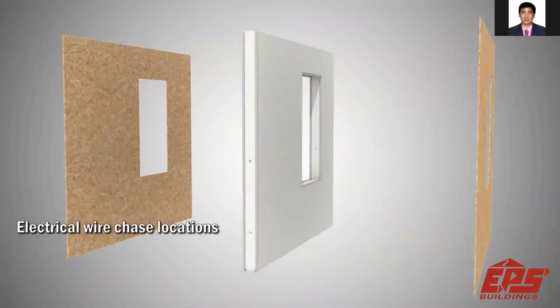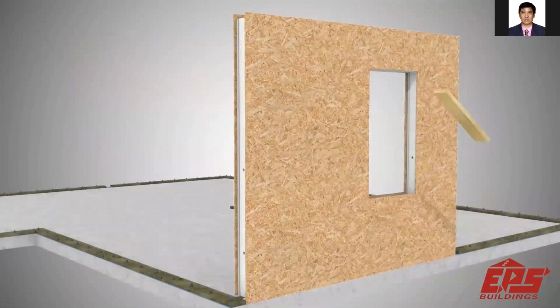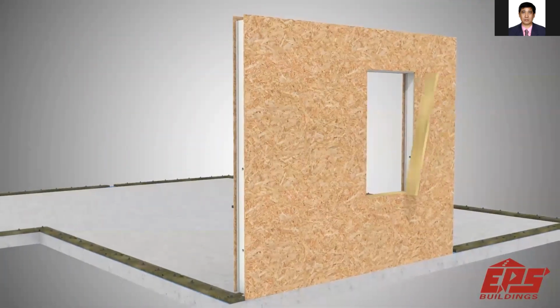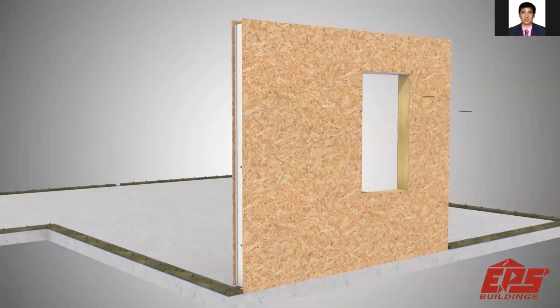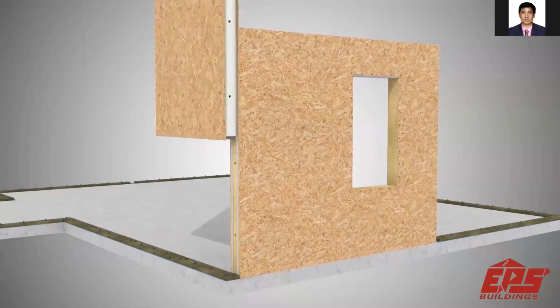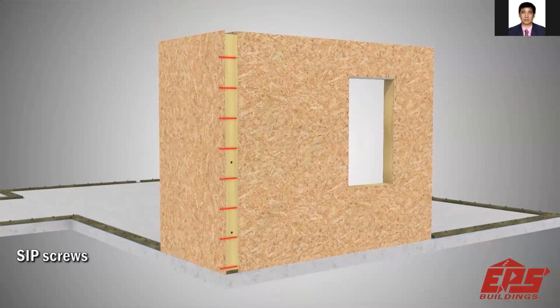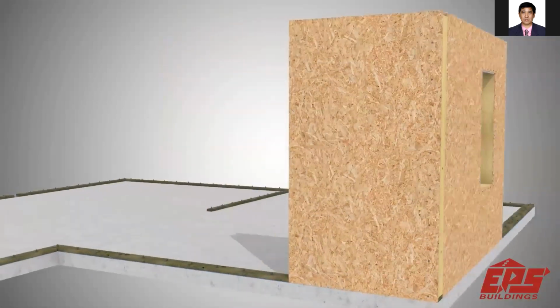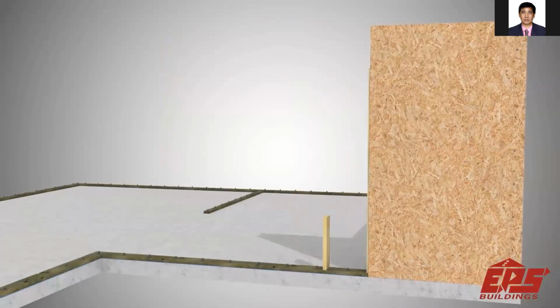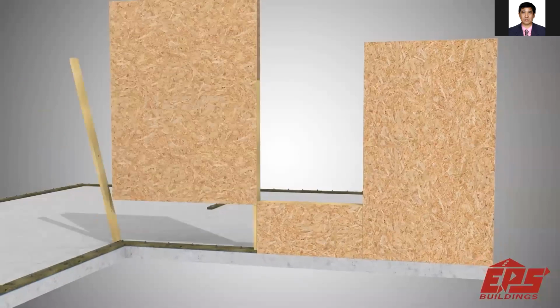Optional electrical wire chases can be placed horizontally or vertically in the panel. Wall panels are installed over and fastened to a base plate. Assembly starts by fastening corner panels together using both interior and exterior surface studs and SIP screws. Sealant prevents air and moisture from penetrating the panel. This foam is used to seal along the bottom of the panel as well as in between each panel joint.